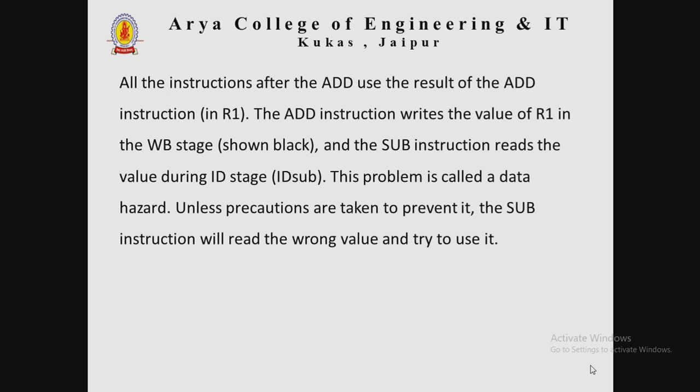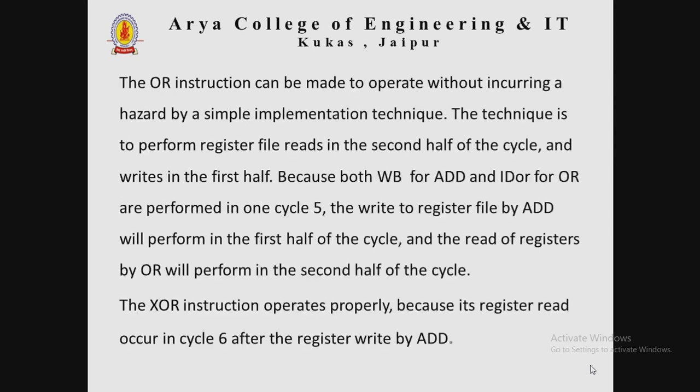The OR instruction can be made to operate without incurring the hazard by a simple implementation technique. The technique is to perform the register file reads in the second half of the cycle and writes in the first half.